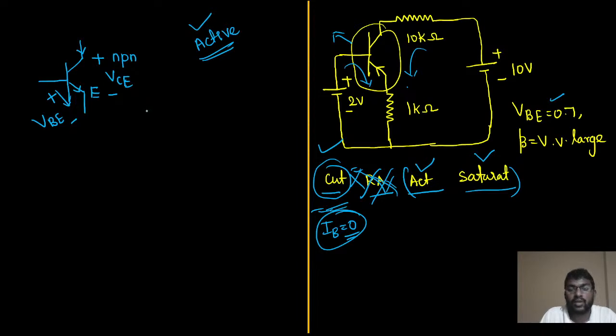But here we are dealing with what type of transistor. If you observe the transistor configuration properly, let me show you. The direction of the current is given inward. So what should we do? It should be like this: entering point plus, leaving point minus. Same for emitter to base voltage, or base to emitter voltage, but here we write emitter to base voltage because we are going in the opposite direction. So this will be equal to 0.7 volts.